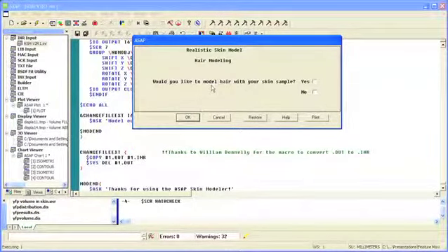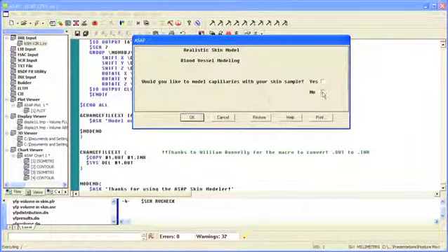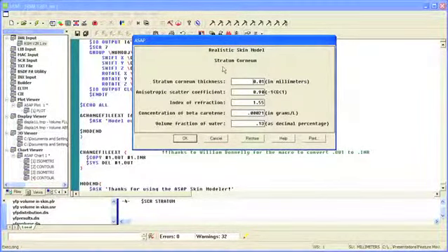The RSM provides several optically relevant and physiologically relevant geometries, such as hair and blood vessel modeling, which we won't examine in this particular model. For each layer modeled, we can examine and change the thickness, the anisotropic scatter coefficient, and the index of refraction. Also, for each layer, there are confined chromophore concentrations, such as beta-carotene and water for the stratum corneum. If we change, say, the volume fraction of water in a particular layer, we can modify that layer to examine states such as dehydration.